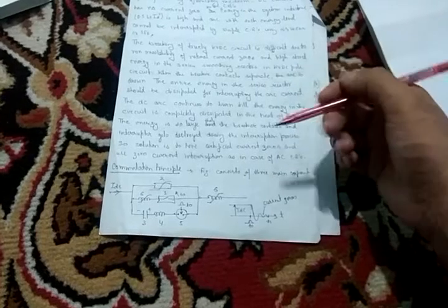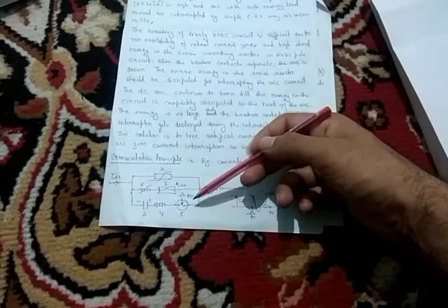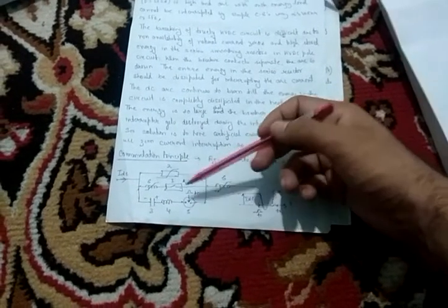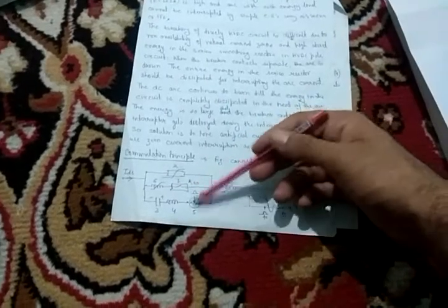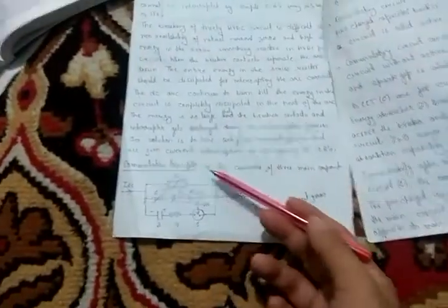So what we have to do is make some artificial current zero. And this is the technique for doing the artificial current zero. This is the main circuit breaker, this is the LC circuit, and here we have this switch, which is called S. So this is the commutation principle.